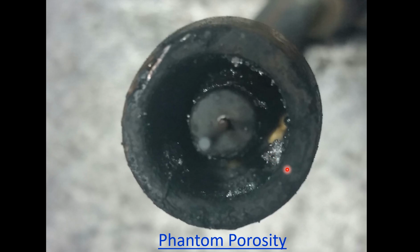But I want everybody to note right here, see these clusters that build up inside of nozzles? We have a situation, and I've had too many of these calls, and I wanted to put it in a presentation, and I call it, for lack of a better word, phantom porosity. So I see this in cells where the guns run a long time, or sometimes a longer time between reaming cycles than they should. And the stations will report porosity that comes and goes. And it'll be over here and over there. It's in no specific place. Now that's key for me when they say I'm getting porosity now and then in no specific place. And what I'll always say is, and I'm telling you this as possibly robotic people, but definitely people that are going to be some of the first people to lay your eyes on a weld.